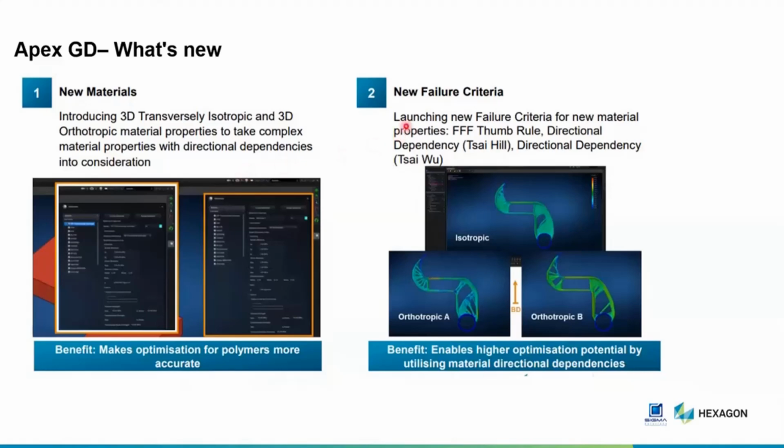At the same time, you can define the failure criteria in each direction so that it can be considered during the lightweighting or topology optimization process. That way you will have better control on the design, so that you need not really go for a detailed durability analysis.